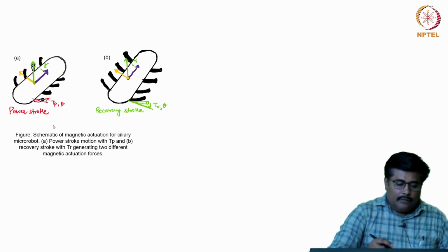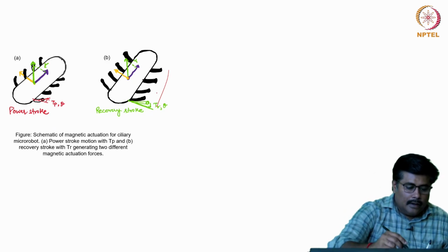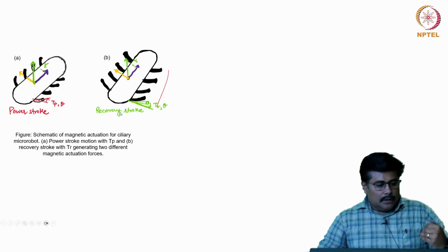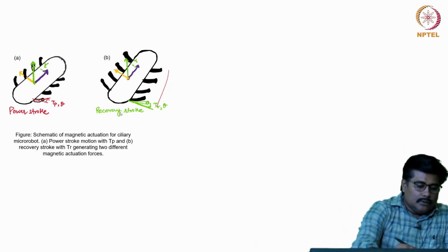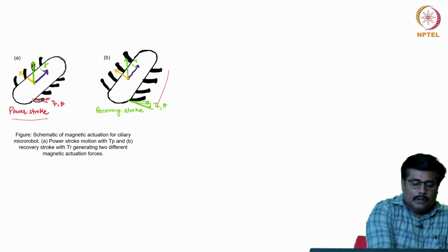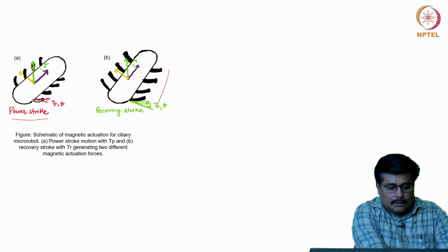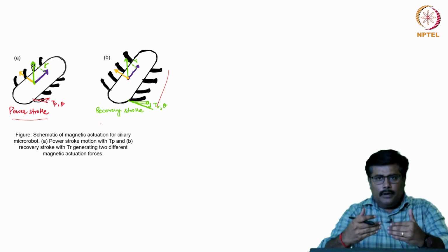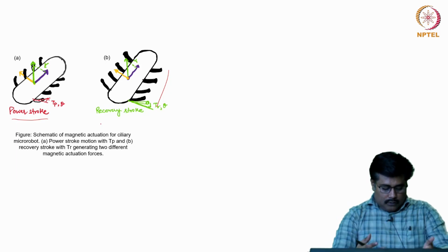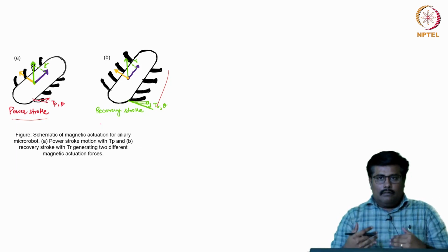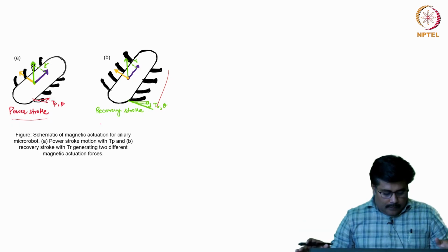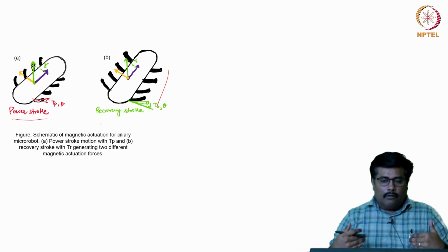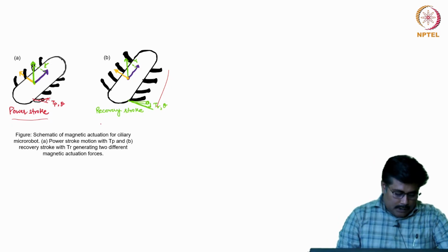a kind of locomotion. In fact, this is a ciliary based micro robot, where we have two different types of locomotion which contribute to it. One is called a power stroke, which is used for propulsion in a forward stroke, and then we have a recovery stroke where there is going to be a lift, a push or a recovery which will take care of the micro precise locomotion exhibited over here.